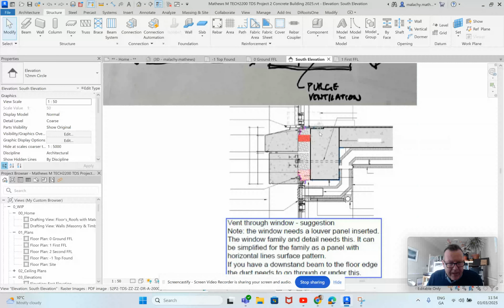One of the main advantages is that it provides a platform, kind of a construction platform. You can see this is the top edge of a precast concrete unit, and we can get a fixing in here, which will fix into that unit. This is the bottom of the same precast unit, and we can get a plate in across there to fix that as well. Then this detail is finished off with a false ceiling and a little bit of ductwork which allows for some mechanical ventilation to go out through the window there.